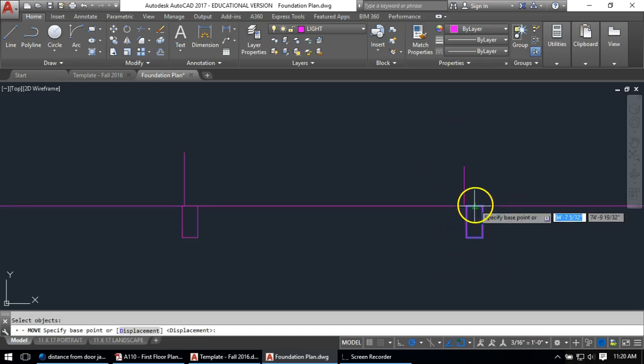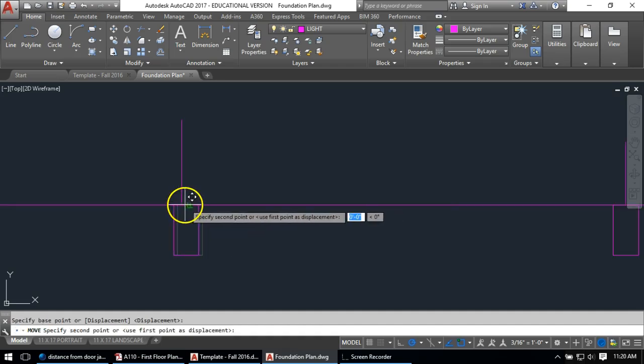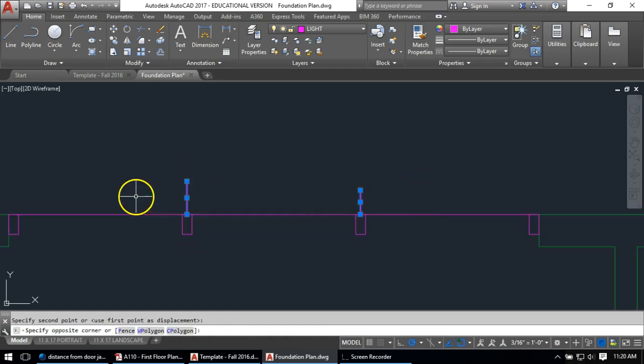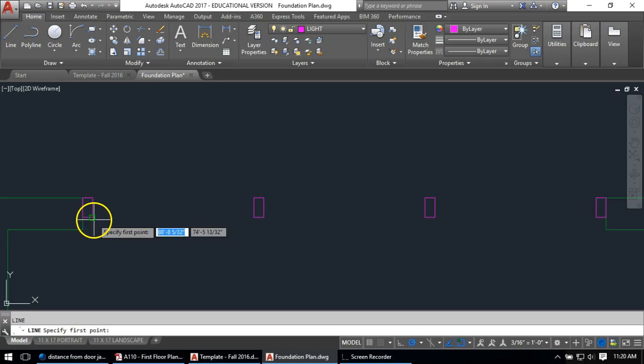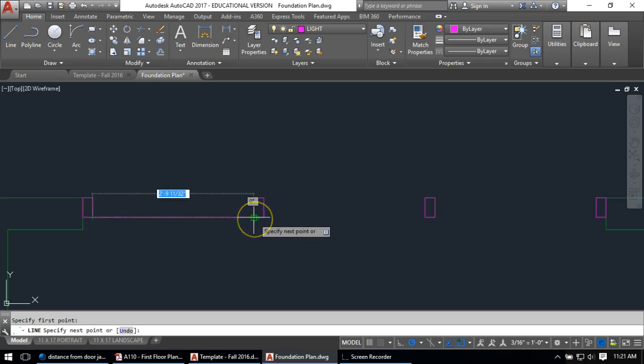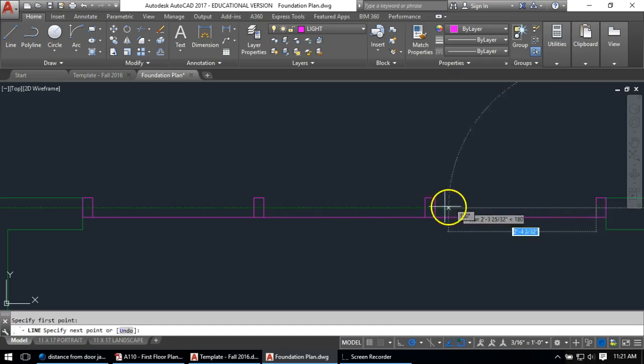And now I can move from the midpoint of that shape over, midpoint of that shape over. Now that's the way I've interpreted this based on the information provided here. If I had the window schedule and knew more about these windows in detail, it might turn out that interpretation is wrong and that the opening had to be wider. I think that's a valid interpretation as well.